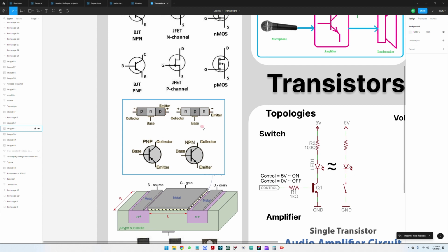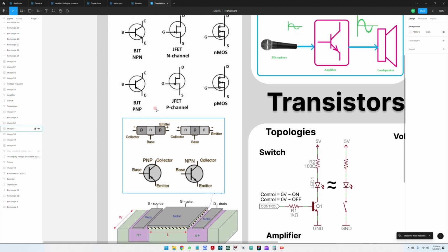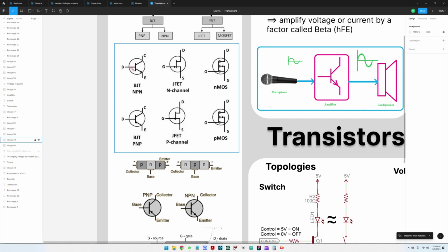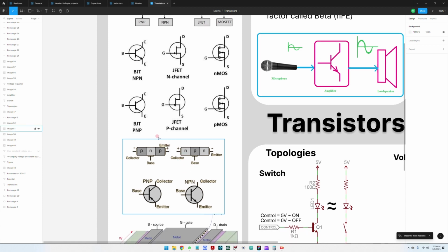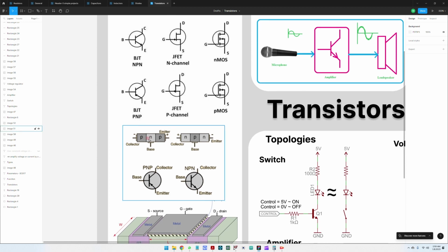And we know from the diode video that a diode conducts from a P to an N substrate. So these here can be considered diodes for the bipolar junction transistor. Even in real life they have about 0.7 volts, very similar to a diode's voltage drop. Some have even smaller, depending on how large one of these layers is. So basically, here you have a diode.